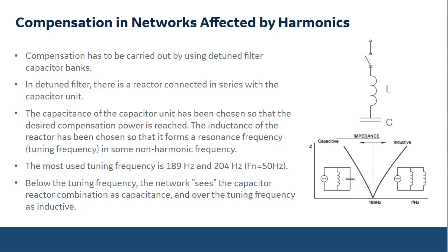So it's also inductive. There's not possibility to be any resonance because the transformer winding is inductive, and now our capacitor bank impedance is also inductive above this 189 Hertz frequency.